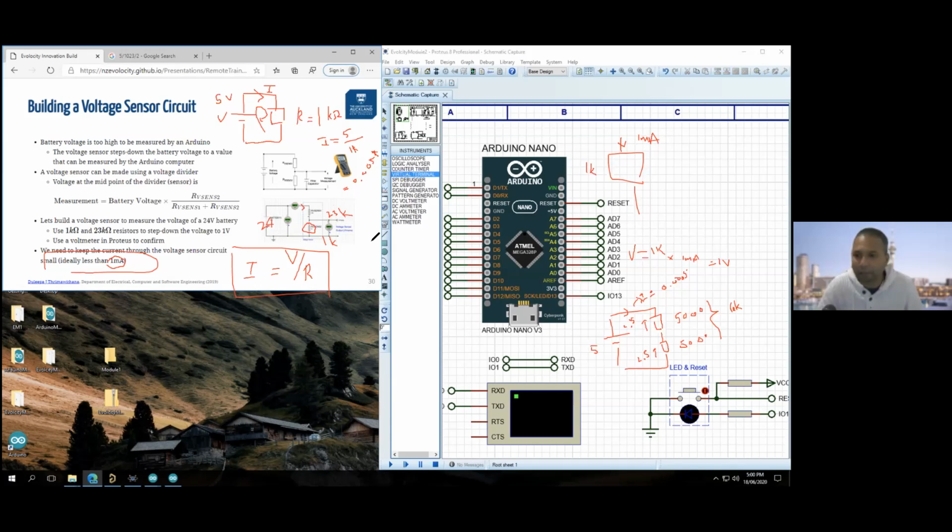Exactly. So if you had 24 volts and a 16 kilo ohm resistor, then an 8 kilo ohm resistor, would you get 8 volts? If the bottom one is 8, it depends on which one is 8 though. If you swap them around, whichever is bigger gets the bigger voltage. So is it fractional? Yeah, it is a fraction. Okay, that makes sense.